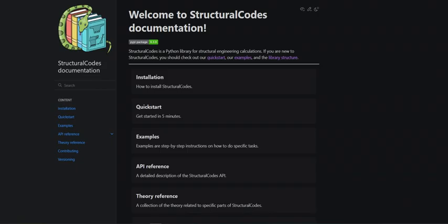We also have the calculate strain profile based on a set of axial force and biaxial moment, which is really useful for calculating the response of the section to a given load. Typically, that could be input to a crack width calculation, for example. Yeah. And you have the inverse of that, so integrating the strain profile in order to get the axial force and biaxial bending based on strain and 2 curvatures.